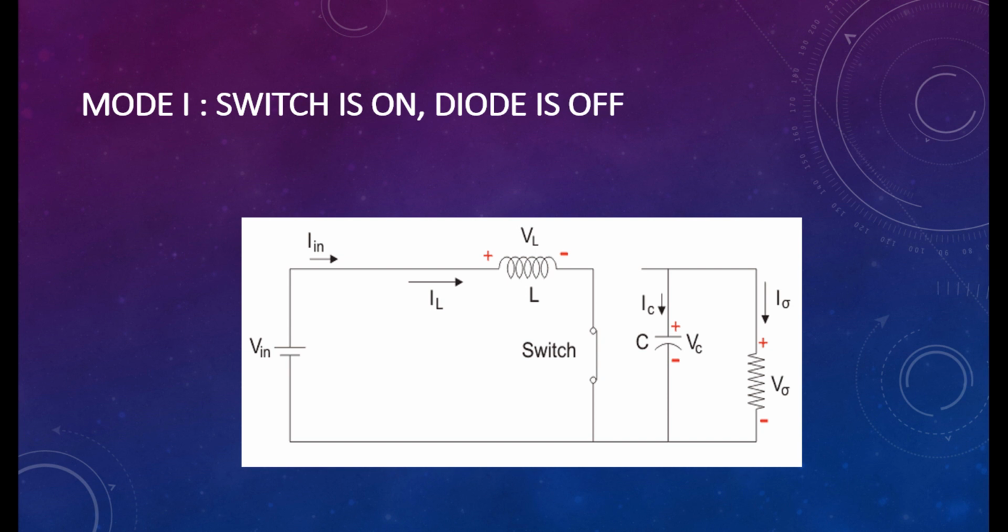While performing the analysis of the boost converter, we have to keep in mind that the inductor current is continuous, and this is made possible by selecting an appropriate value of L. The inductor current in steady state rises from a value with a positive slope to a maximum value during the on state and then drops back down to the initial value with a negative slope. Therefore the net change of the inductor current over any one complete cycle is zero.